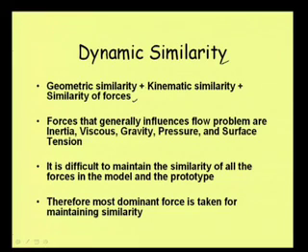Well, now this is very critical because, maintaining similarity of forces in the model and prototype, we need to think about what force, because in a fluid flow problem there are so many forces that can influence the flow. Generally the forces that influence a flow problem are inertia, then viscous force, then gravity, pressure and surface tension. Elastic force will also be dominating if it is a pipe flow case.